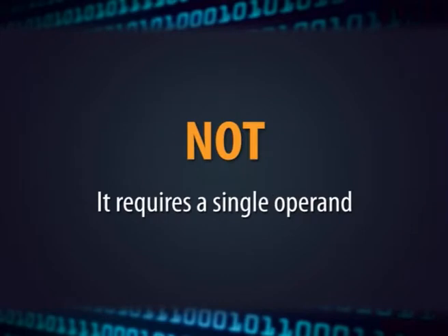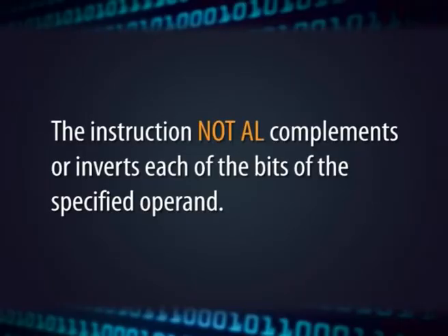The next instruction is the NOT logical operation. The NOT logical operation requires a single operand, unlike AND, OR and exclusive OR, which require two operands. The instruction NOT AL complements or inverts each of the bits of the specified operand.